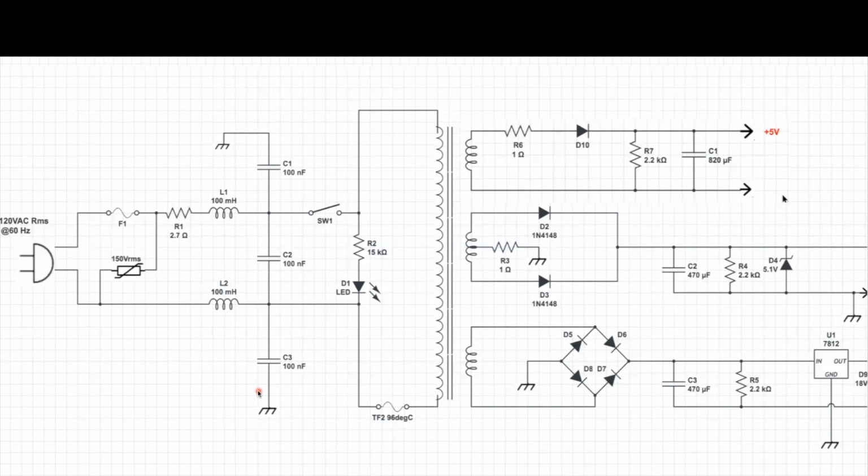Usually it's electromagnetic interference. Here's our easiest component. Who could tell me what SW1 is for? It's a switch, and it does what? There we go. It completes the circuit and turns our device on, right? So right now we're all powered up to the switch. We're overcurrent protected, overvoltage protected. We're cleaning up the power line. We have a clean 120 volts.